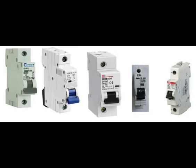When you see the MCB, you will easily find the specification written over it. Here you can see that it is a B type 32 ampere MCB. Here it is C type 16 ampere. Likewise it is D type, K type and Z type of MCB, and all over here its specification in ampere capacity is written. So all these, as you can see, are one pole MCBs. In the same way you can have a 3-pole MCB, and the specification is also written there on the MCB.